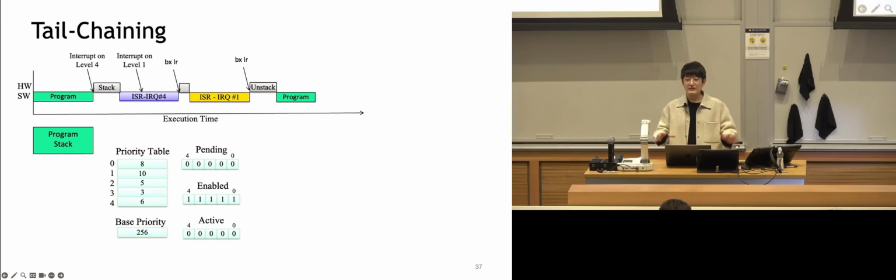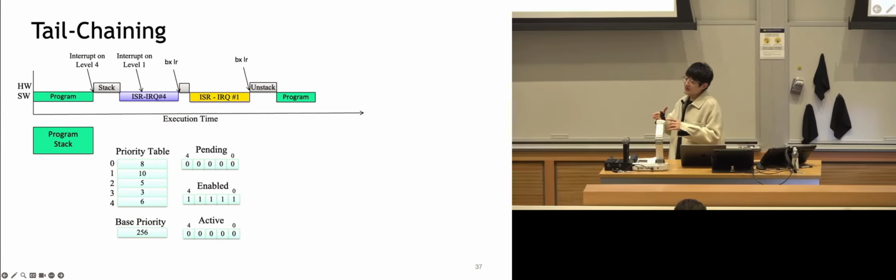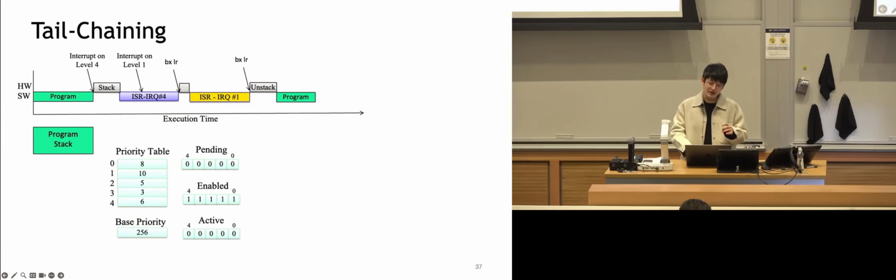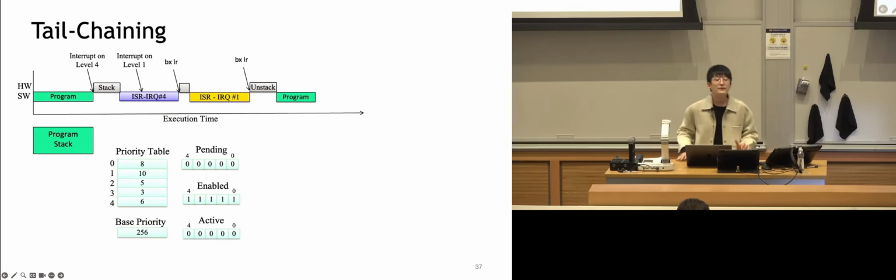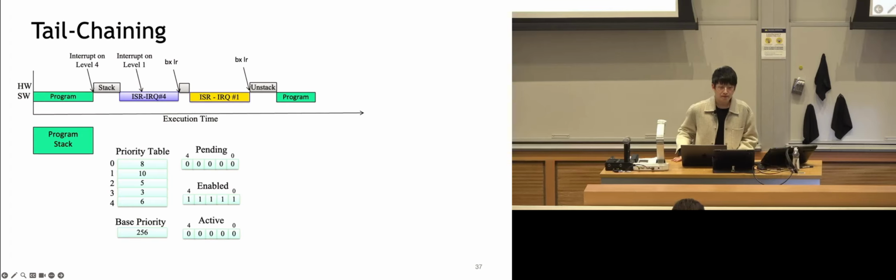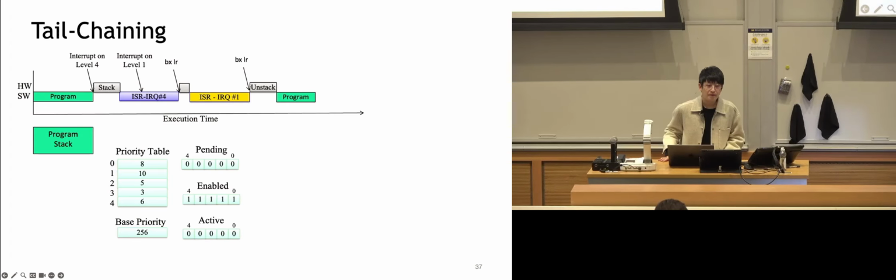And the late arrival basically happens during the stacking. There's a higher priority interrupt coming, so it still does stacking, but just one stacking instead of 2. So in the case of late arrival, if we haven't branched to the lower priority interrupt yet and then we go to the higher priority one, would the lower priority one only go from pending to active later?